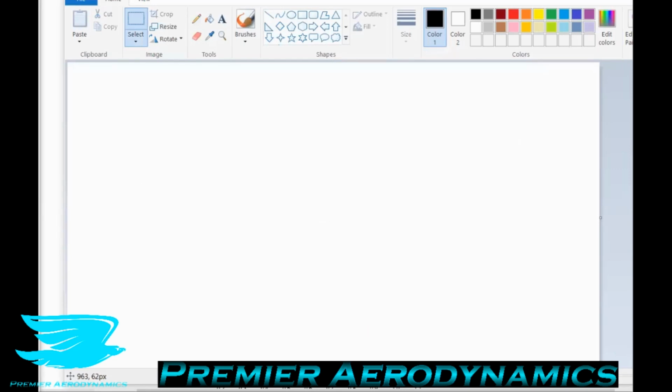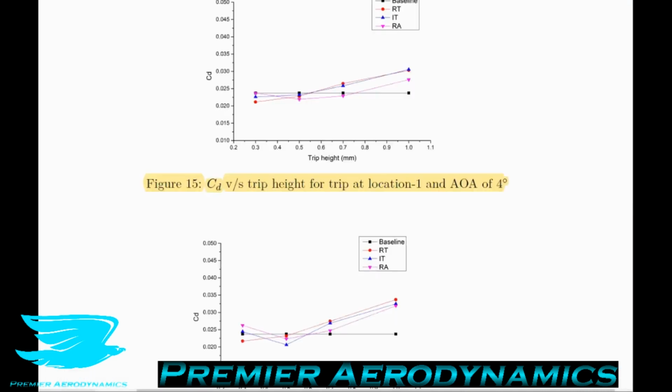So let me cover quickly why a boundary layer trip would get rid of an LSB. As I mentioned, if we have an LSB over a surface, that is because initially we have a laminar flow. If we don't have a laminar flow, an LSB cannot form, because an LSB has to form from laminar flow, which then transitions when it detaches. So what we're doing is getting ahead of where the LSB would usually form. Let's say it forms halfway downstream here. Before that, we put the boundary layer trip. So the airflow hits here, then it turbulates, and as it reattaches behind the trip, it is now turbulent. Once it gets to the halfway mark, where the LSB would usually form, it's already turbulent, so an LSB will not form. So that's how it can get rid of LSBs, not to mention turbulate the boundary layer and transition it from laminar to turbulent.